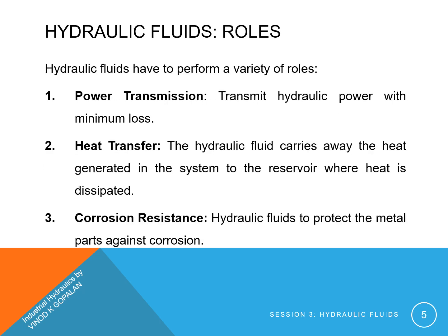Roles of hydraulic fluids. Hydraulic fluids have to perform a variety of functions. First is power transmission. The most important function of hydraulic fluid is to transmit hydraulic power with minimum loss. Next is heat transfer. The hydraulic fluid carries away the heat generated in the system to the reservoir where heat is dissipated. Next, corrosion resistance. Hydraulic fluids protect the metal parts against corrosion.